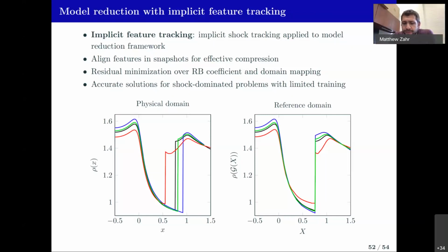I mean, the main issue with it is going to be that the turbulence is going to kick up some unresolved features, obviously, because of the scales that are involved. So how the sensor, the objective function that we have, will respond to that versus discontinuities is not obvious, because it could just cause the mesh to freak out where all these turbulent features are.